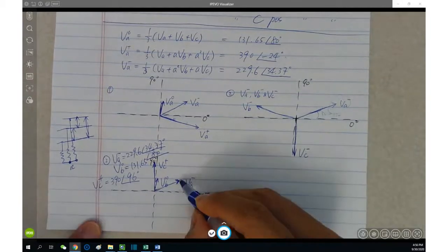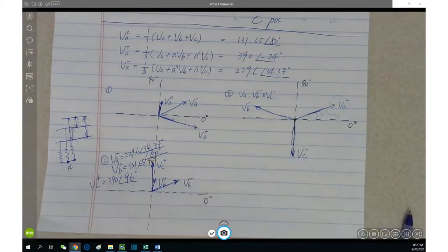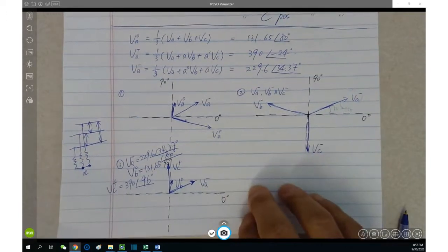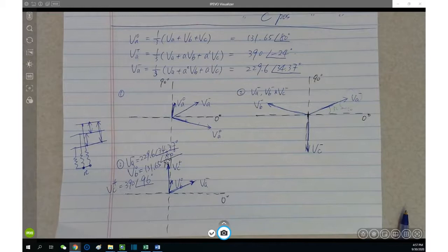Does it make sense? Any questions regarding this problem? Where did we get VB0? VB0 is equal to VA0. Remember zero sequence? Okay, gotcha. So once again, as long as you have the symmetrical components, you know anyone else among those 9 I just mentioned, right? 3 by 3, 9 components.